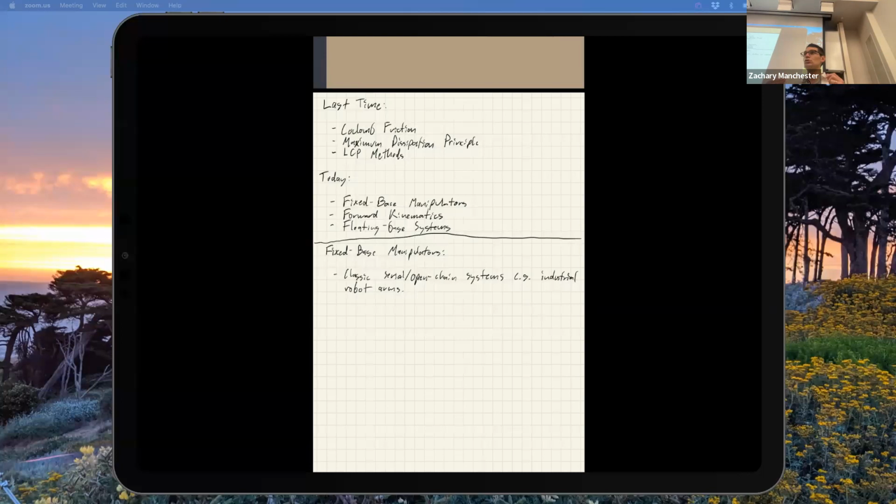The problem comes if you try to use a stock dynamics package that uses Featherstone's algorithm, RNEA, one of these standard algorithms that assume an open chain. When you do that, the hack to make it work is you unroll the loop to write down the dynamics in these packages, and then you add on a constraint after the fact to bolt the loop back together. So if you want to simulate a 4-bar with like MuJoCo, one of these things, you end up having to do this.